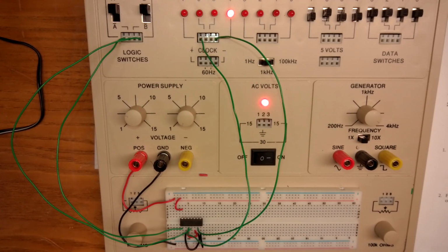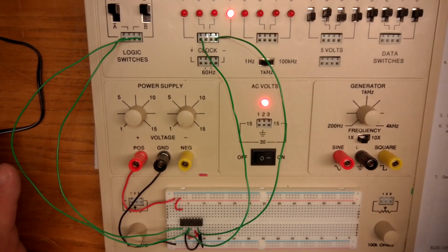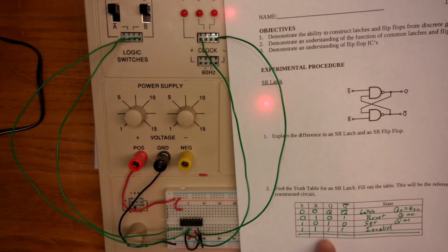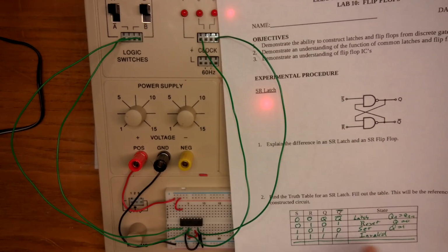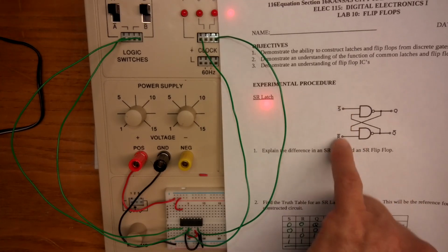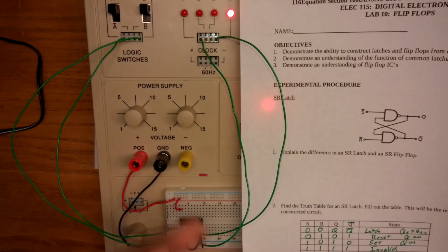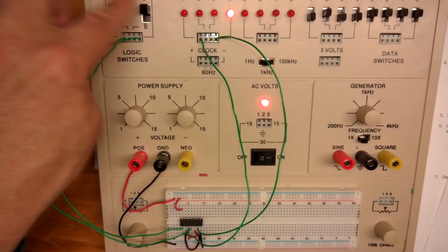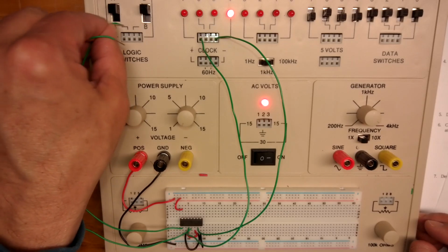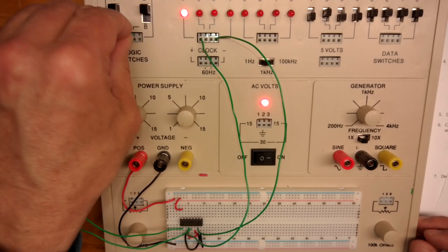Now, I'm going to let you know something here. Most students would build it this way, and it will be perfectly fine. However, your truth table wouldn't perfectly match this, and that's because this input, while it's an SR flip-flop, it's an SR latch, but anyhow, R and S are R0 and S0. To account for that, I can either in my mind shift them, or because I'm using these logic gates at the top, I'll just plug in, instead of A, I'll use A0. Instead of B, I'll use B0.